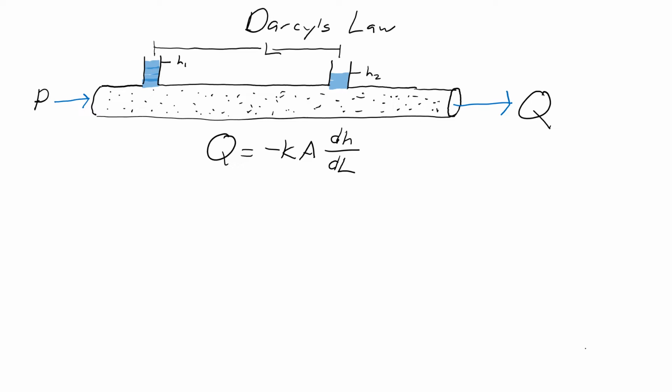Once you have the geologic cross-section done, you should be able to answer the rest of the questions fairly straightforwardly, okay? It's going to require you to look at the different rock types, figure out which might be confining layers, which might be good aquifers, how deep they are, how far down you have to go to drill to get them, things like this. So this is hopefully kind of a real-world exercise. People have loved it and hated it both at the same time in the past. It's more work than this assignment that you just did. Not by a lot, but the cross-section does take a little time. Once you have the cross-section done, the lab itself, the homework itself, is not terribly difficult.